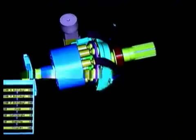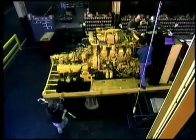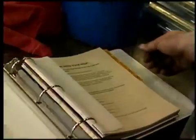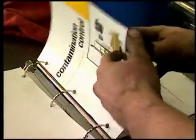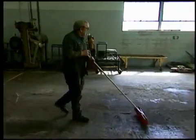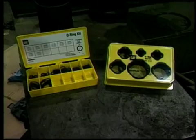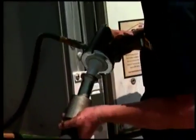To reduce contamination, Caterpillar is committed to designing and building clean components and machines, and providing information, tooling, and training to help dealers and customers maintain clean components and machines. But it takes a joint effort at all levels to control contamination, starting with the contaminants you can see. Keep floors and work areas clean. Protect parts during assembly, repair, and storage. Clean hoses during assembly.